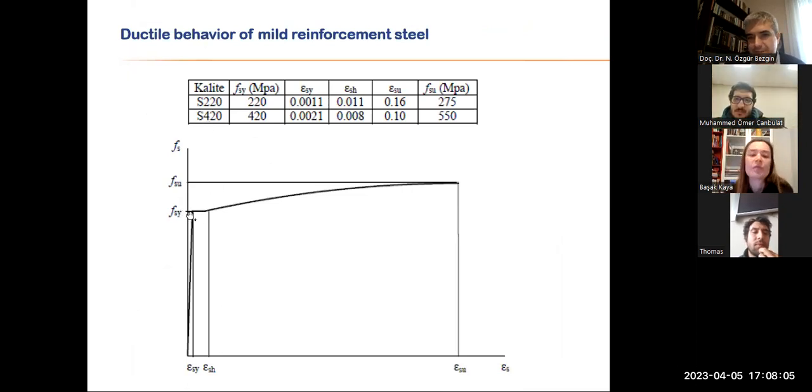So this is where you are working. This little zone is where we are working, the elastic zone. And then there's a strain, this plateau, the yield plateau, and then this is the strain hardening region. We are working all the plastic stuff, all this fun, good stuff is happening in this region, maybe slightly ahead. Why am I dealing with this part? Because in the earthquake or seismic loads, it may fail. If it fails, we have to know how much flexibility or yielding we have. I think it's an important part: before the failure, how much it's going to yield.